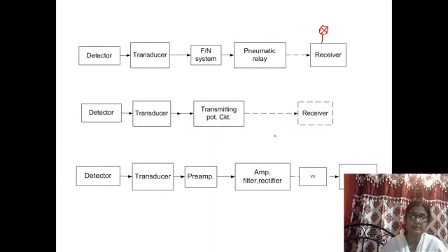Say for a level control system, for a tank unit, if the level changes, there is a certain level, and say there is a float for measuring the level. Then if the level changes, accordingly the float position will change, and that will be connected as a potentiometer circuit.